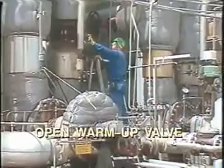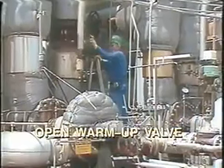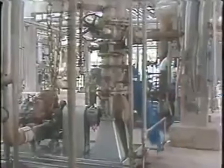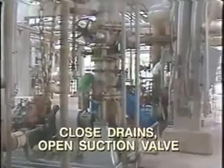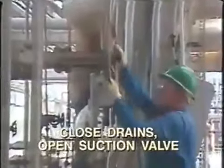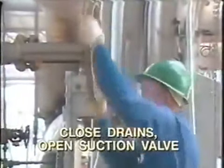This may prime the pump as well as warming it. When the pump is warm, close the valve. Next, close all drains and open the suction valve to the pump. Then prime the pump. Be sure the priming is complete before starting the pump.